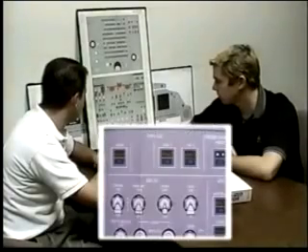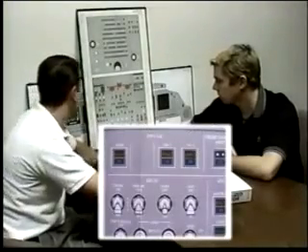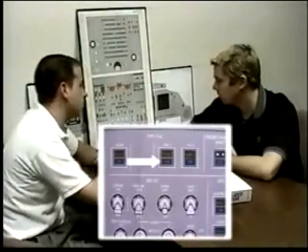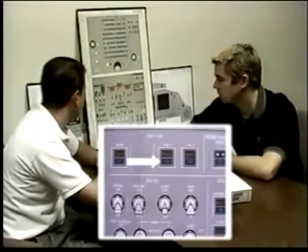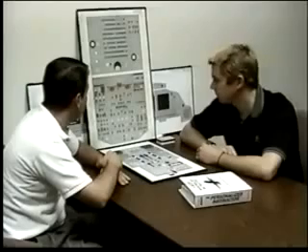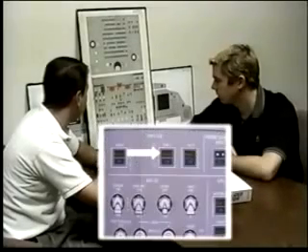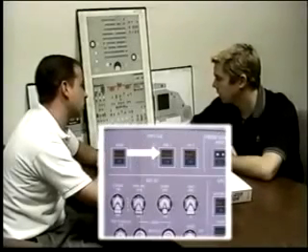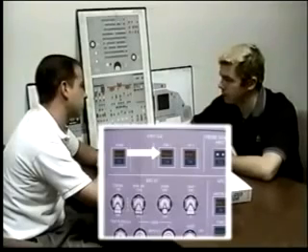Engine anti-ice. You select engine anti-ice to on. What are you heating? The engine itself. Anything else occur? Yeah, you get automatic ignition. What about fault light in engine anti-ice? That indicates a valve in transit or a valve disagreement.